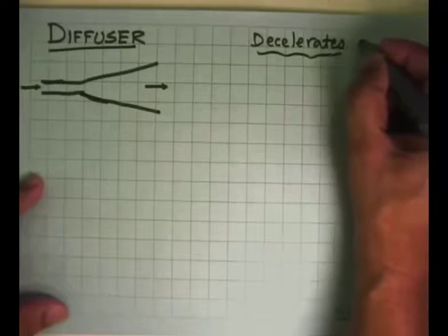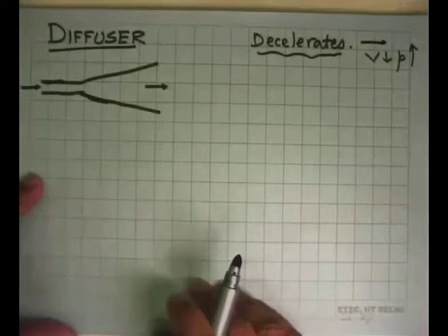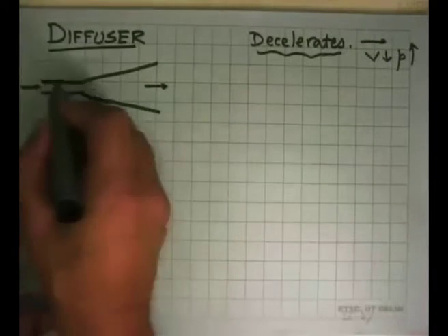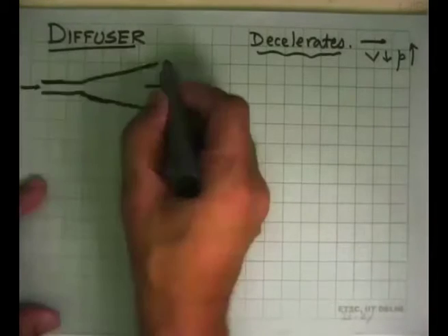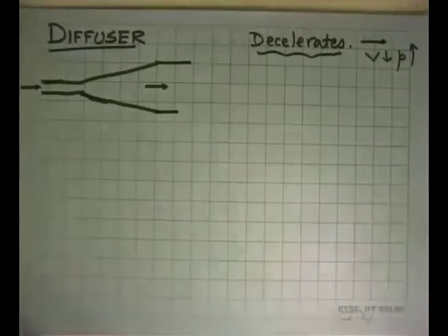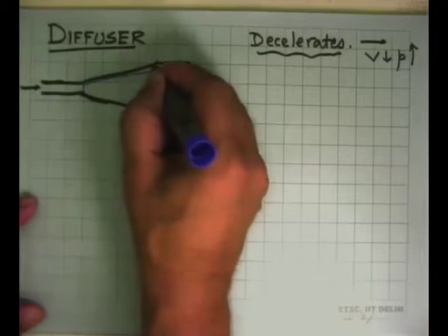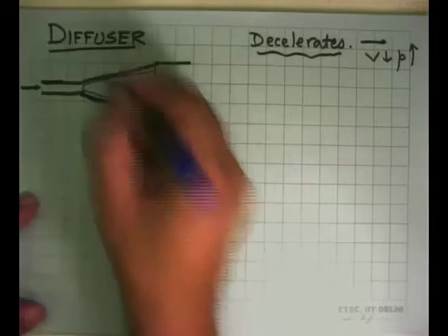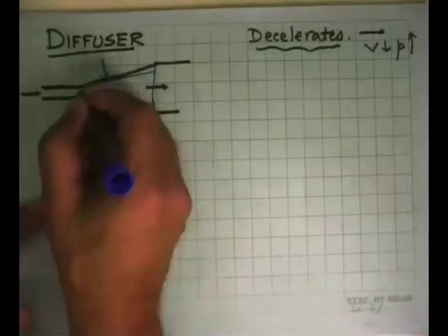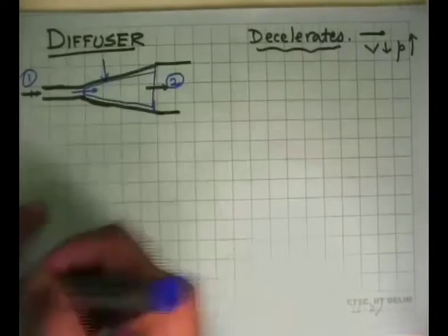That means in the direction of flow, the velocity goes down and pressure goes up. So what's happening here is that we have a flow coming in and then the area opening up, and the flow goes out over there. We say that the diffusing part is the one where the area is large. So this is our diffuser, the control volume. This is the system boundary, you can say. And there is one inflow taking place here. So this is state 1, inflow into the system, and the outflow is state 2.